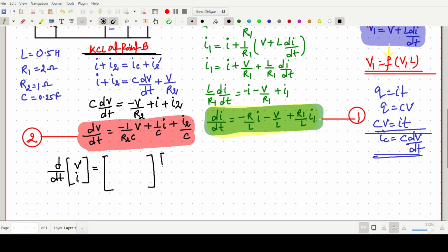Okay, and this value will be our v I. We have to use these two equations plus some matrix into the current sources, that is our I1 and I2. Now we have to put the terms in a 2 cross 2 matrix.